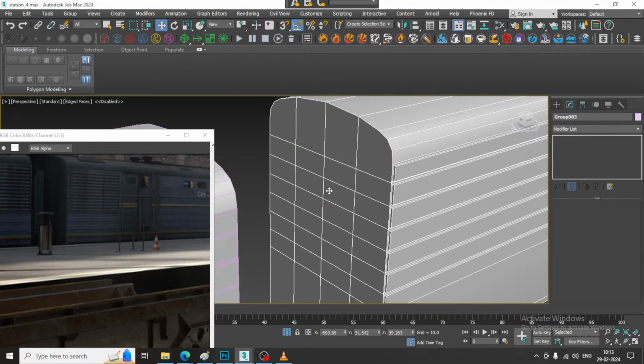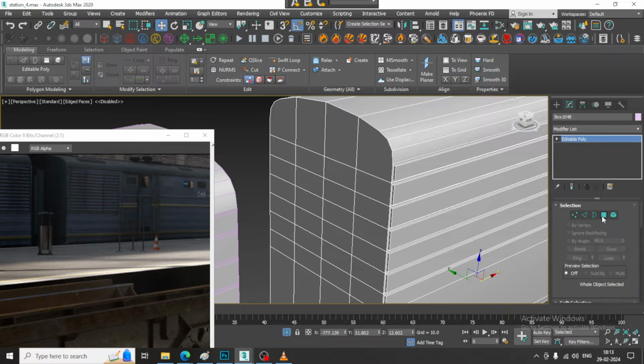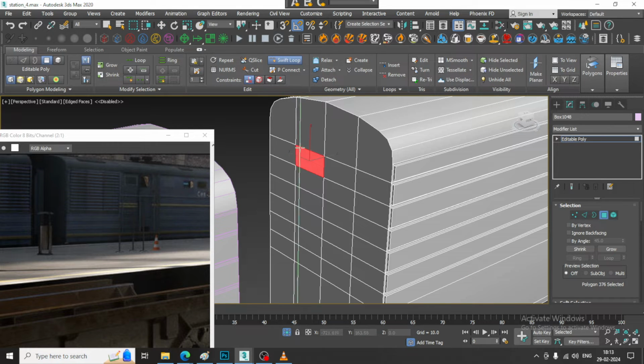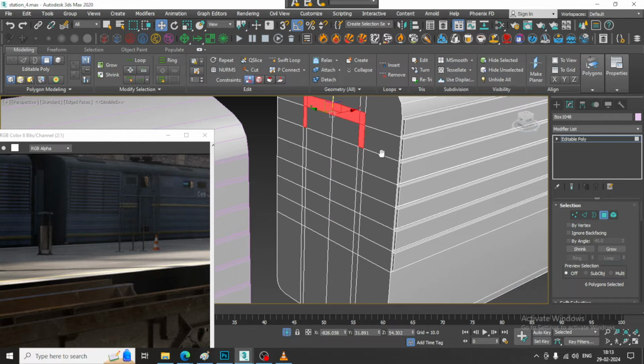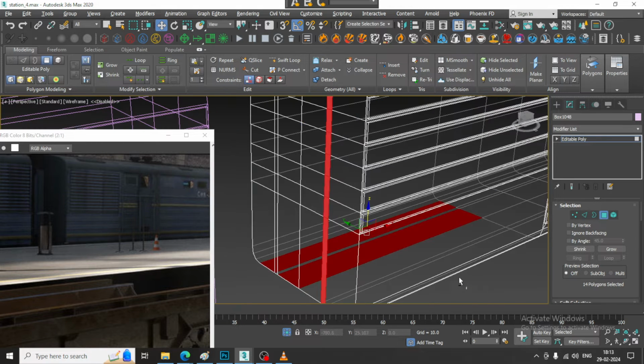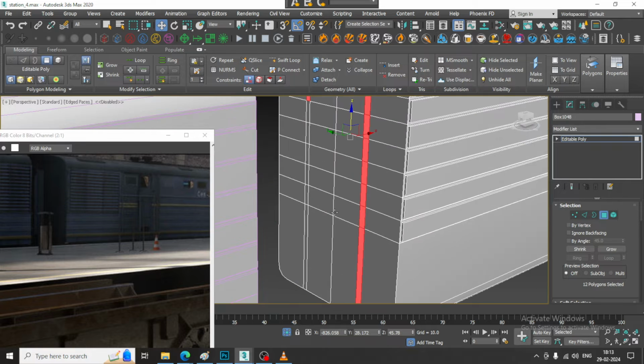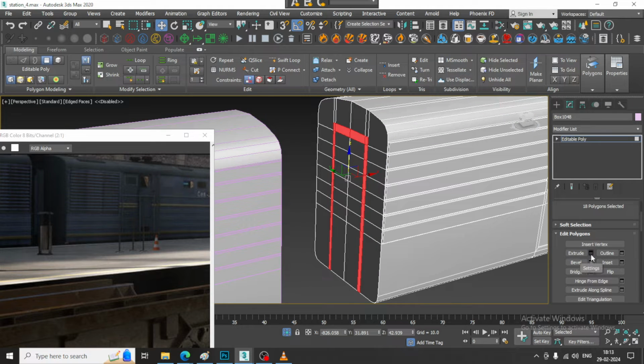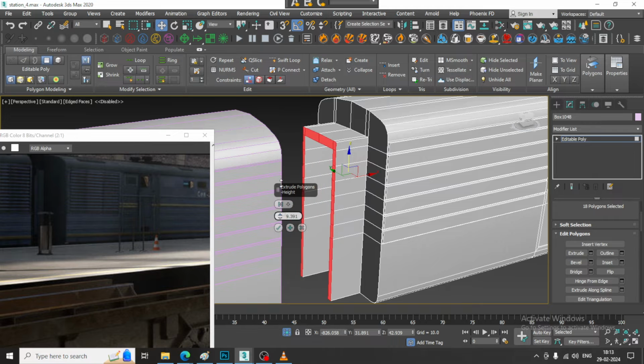So let's select the polygons. You need to ungroup it if needed. So I'll again go over here, let's select this, let's put one swift loop, select the polygons, so I can just exclude this stuff. So just extrude that part out a bit, this way if needed.